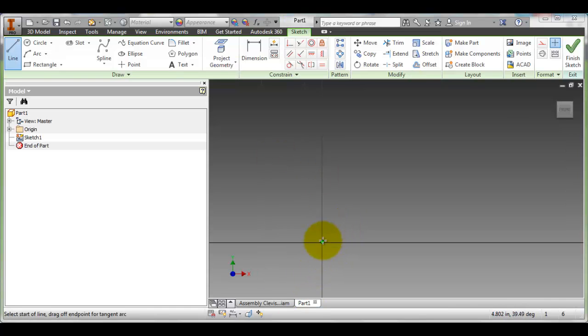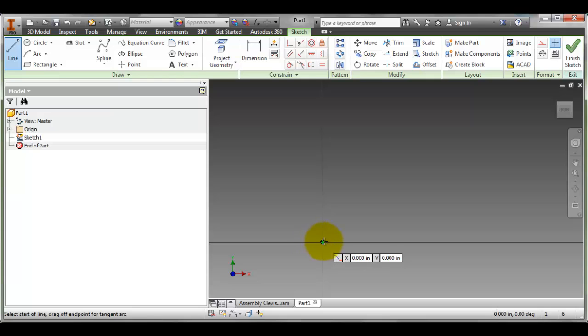And so this time what I'm going to do is to draw the line knowing the distance. So I'm going to go back up to the line command. I'm going to start again at the origin, and I'm just going to draw this out. And notice that if I move along, I get an image just below my cursor and to the right. It tells me that I'm running parallel to the axis there. So that's what I want. I don't have an ortho command like I do in AutoCAD. I'm going to type in the distance, and notice that it goes in at the box. Now I can hit enter, and now I'm going to draw up.